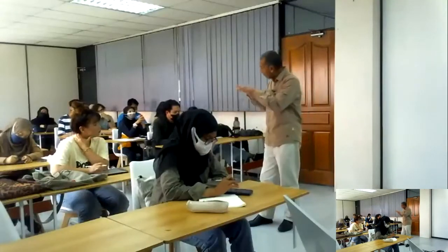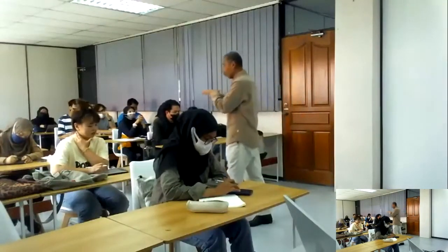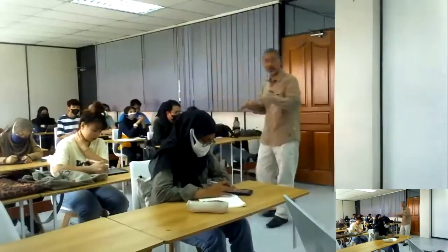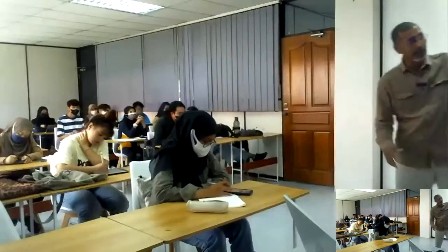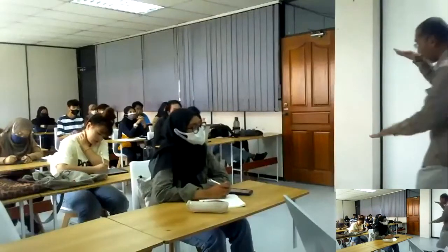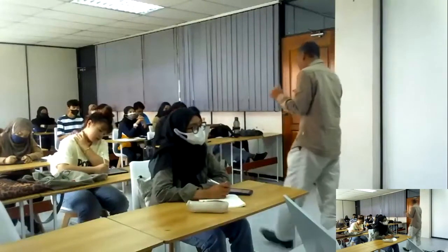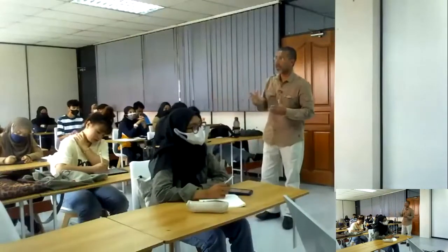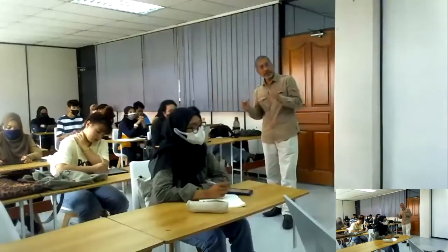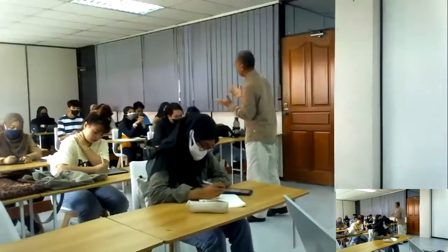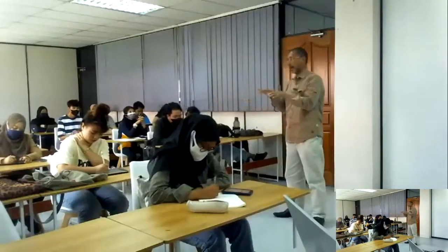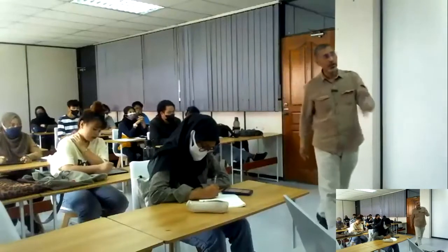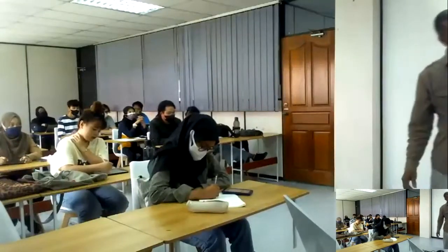The soil adjusts itself and tries to go into a more compact and dense condition because there is loading here. Because of this road, there will be loading when cars move using the road, or a big vehicle like a lorry or trailer. The loading will cause the soil to adjust itself, and when it adjusts, there is dimensional movement within the soil, and that causes this failure.